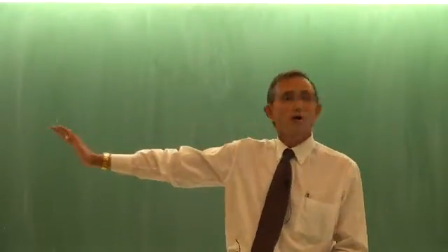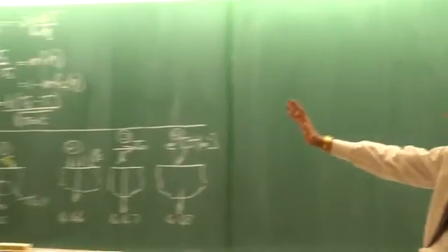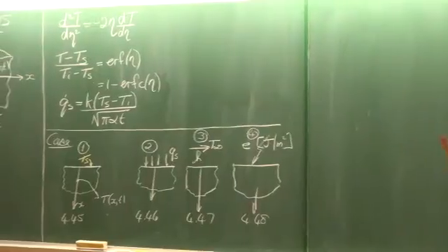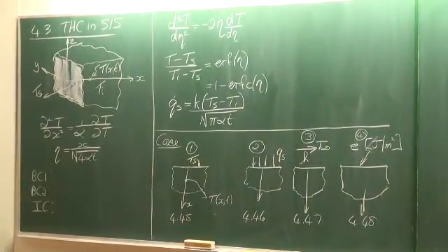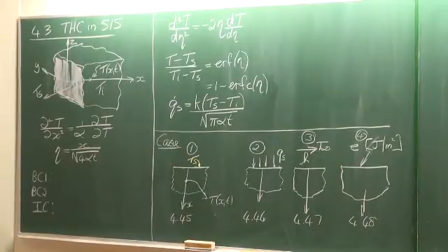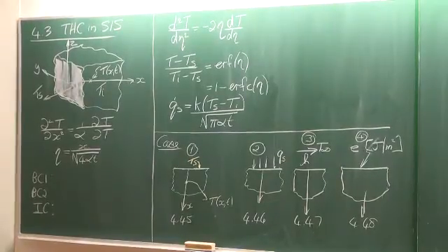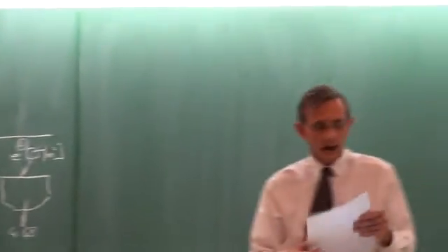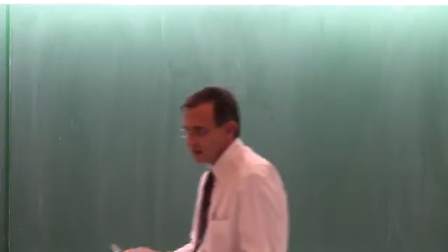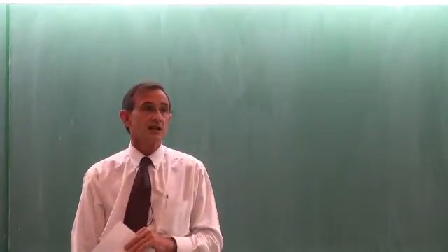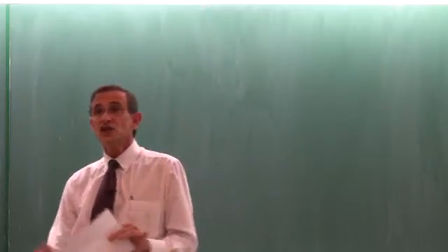That is the theory of transient heat conduction in semi-infinite solids. Let's do a problem so that you can get a better understanding of how to apply it, and specifically this error function, how to use it, and how to do practical problems with it. So the problem is similar to example 4.6 in your textbook, but I've changed it.